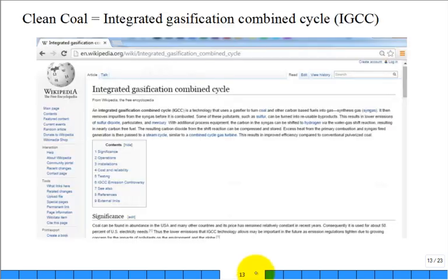Well, about 10 years ago, that was more kicked around. And when we get to the gas power cycle, we'll have a combined gas vapor power cycle, and they'll still have coal as a primary fuel, but they'll try and make it cleaner by first gasifying the coal, making it like a natural gas. You can clean up a lot of the emissions out of it. And then after that power plant, try to capture the CO2 and do something useful with it.